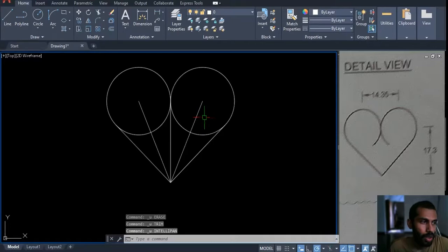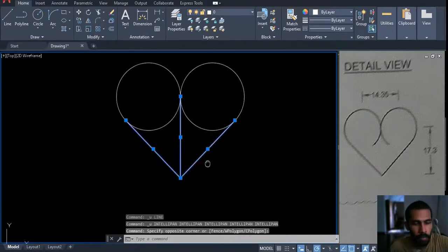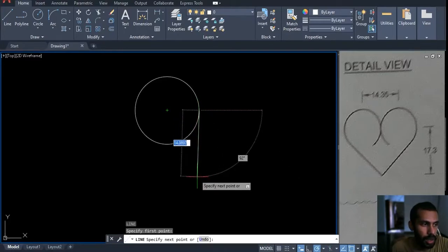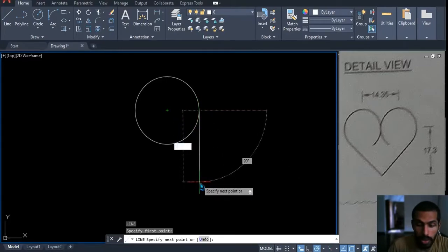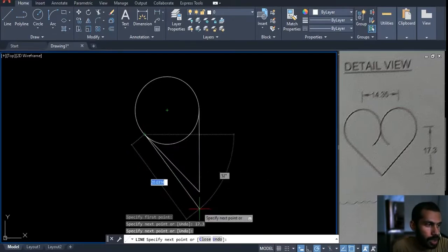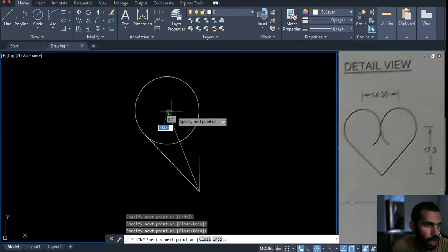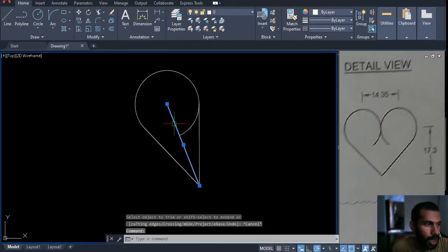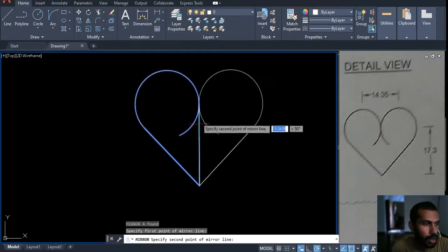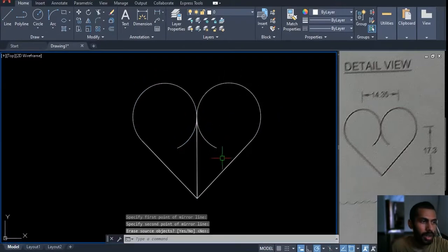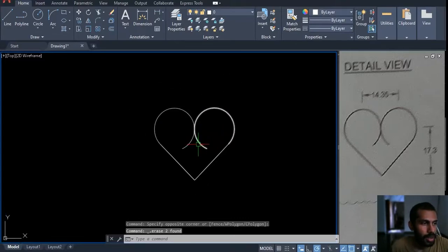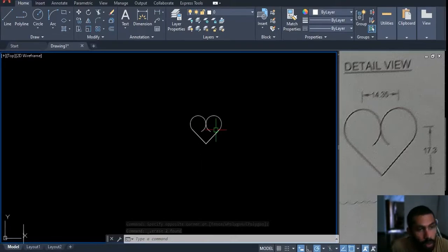If you want to draw a bit faster, take up the first circle, and there is a line here. The line has a length of 17.3. Then draw it to the tangent and draw back to the center, trim this part, delete this part, and turn on the mirror. That is it, and delete this line. Anyways, you'll get this diagram.